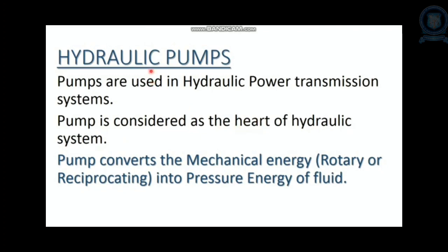Then we can see the second chapter in the first unit, that is hydraulic pumps. You may already have studied pumps. Pumps are used in hydraulic power transmission systems only. Pumps are considered the heart of the hydraulic system. It is the main part of the hydraulic system. The working principle of a pump is that the pump converts mechanical energy into the pressure energy of fluid, or hydraulic energy.